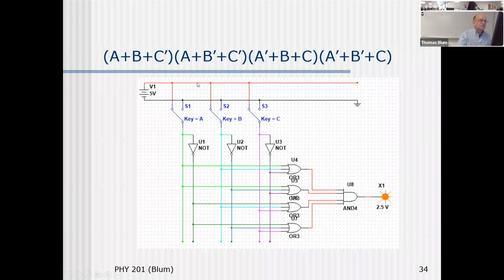These things are junctions. Sometimes I refer to them as nodes. You have to make sure, because sometimes you can have a node that's close to the wire but not connecting, depending on how you made it. If you do this color changing, all those red things should change.